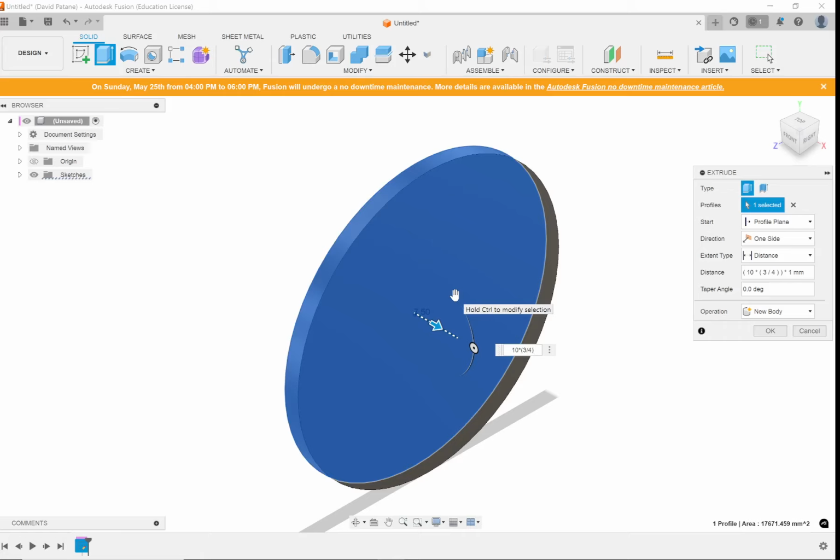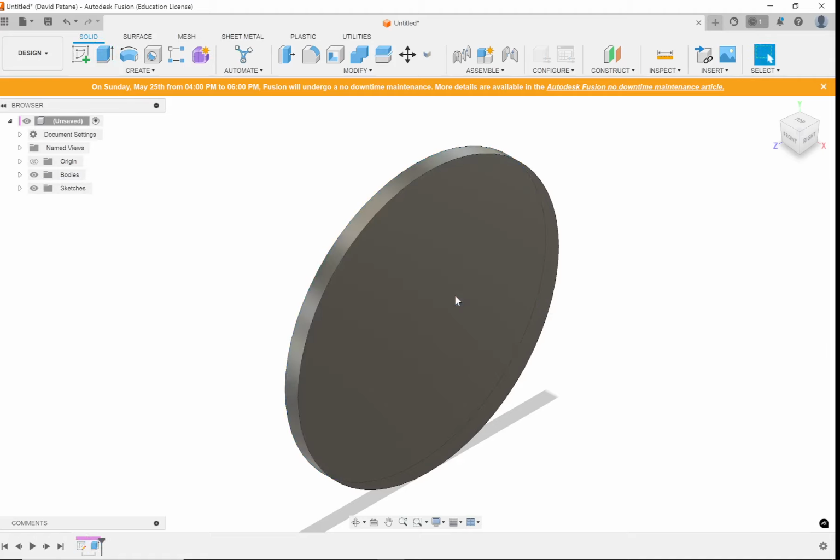Useful if, for example, you're making a fence post and you know you have 10 meters and you need 7 fence posts. How far away will they be? You go 10 meters divided by 7, it'll automatically do that distancing in there. I personally use it only when I'm doing some sort of distance that's going to be a reciprocal, like 1/3, because if I'm putting that in decimal, it's not going to be very accurate, but I can do 1/3 and then it will do it as accurately as the input box will allow.